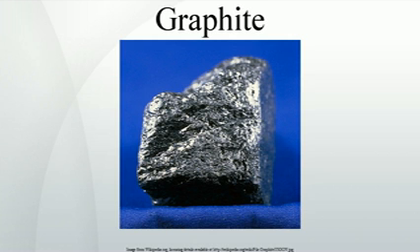The use of graphite is limited by its tendency to facilitate pitting corrosion in some stainless steel, and to promote galvanic corrosion between dissimilar metals, due to its electrical conductivity. It is also corrosive to aluminium in the presence of moisture.